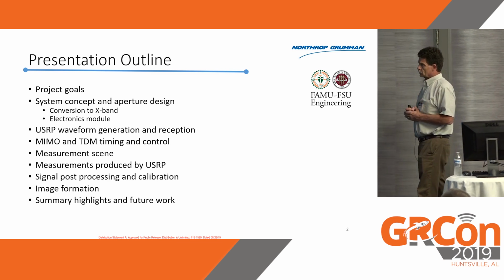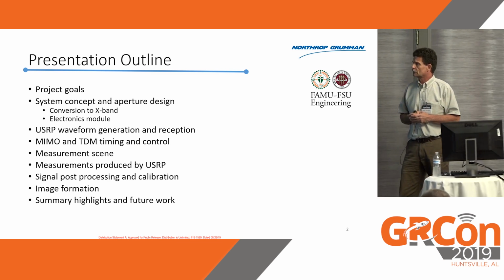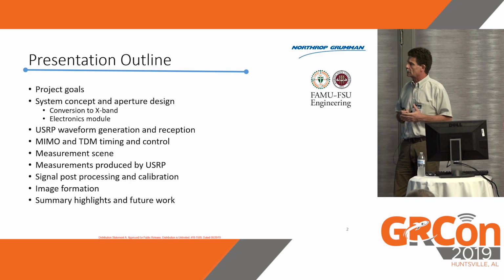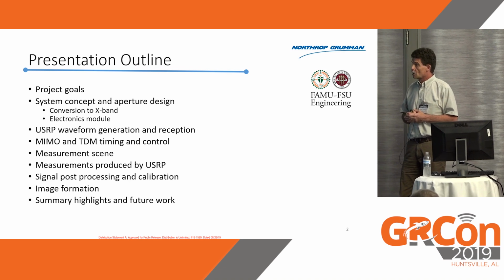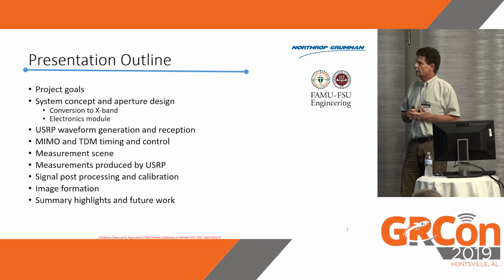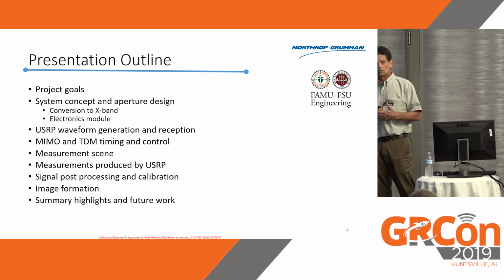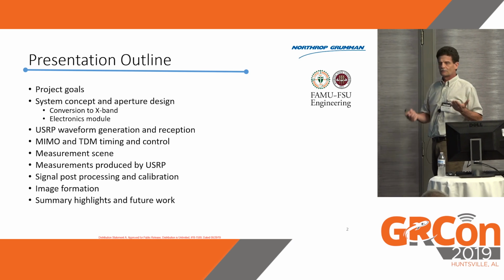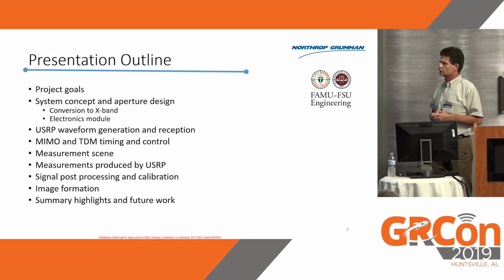And then I'll go into more USRP-centric topics, like how we generate the waveform and how we receive it. We're doing some MIMO and TDM, so we're switching between antenna elements and at the same time coordinating a waveform. So we have some timing coordination to do that's a challenge.